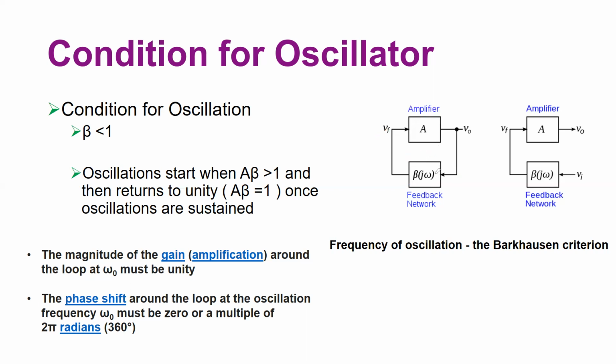That noise travels through the loop, and the feedback network acts as a filter, picking up a single frequency determined by the network of components you use to build it. By filtering only that single frequency, it goes to the amplifier, which amplifies that signal. Again, the cycle repeats throughout the loop and produces your sinusoidal, square or triangular wave, depending on whether it is a linear oscillator or a non-linear oscillator.